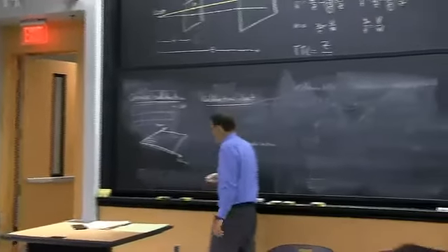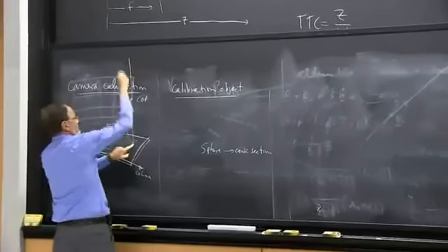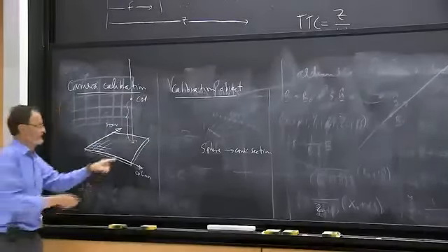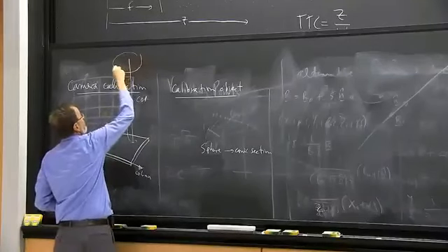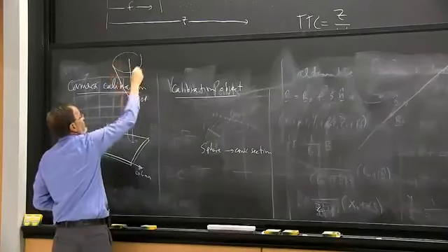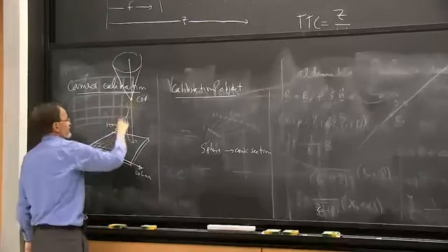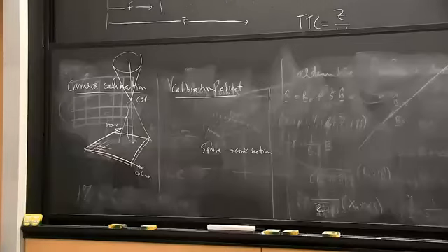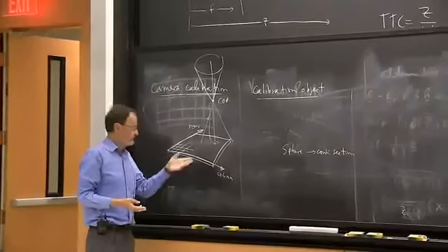And so if this, for example, if the sphere was directly above on this line, its projection would be a circle, right? If the sphere is up here, and how do I know that? Well, because I connect the sphere to the center of projection, and I get a right circular cone, and I extend that down here and intersect it with this plane and intersect the right circular cone with a plane perpendicular to its axis, and you get a circle.